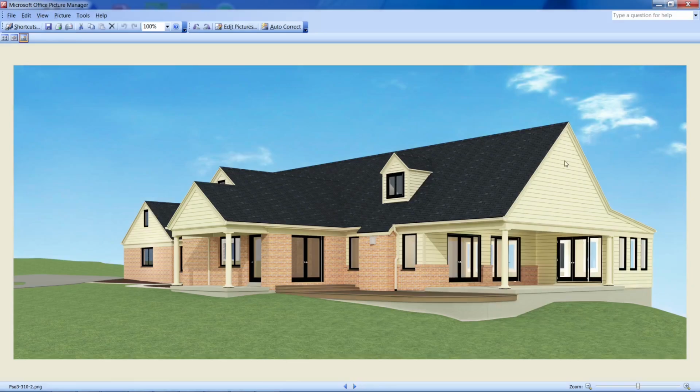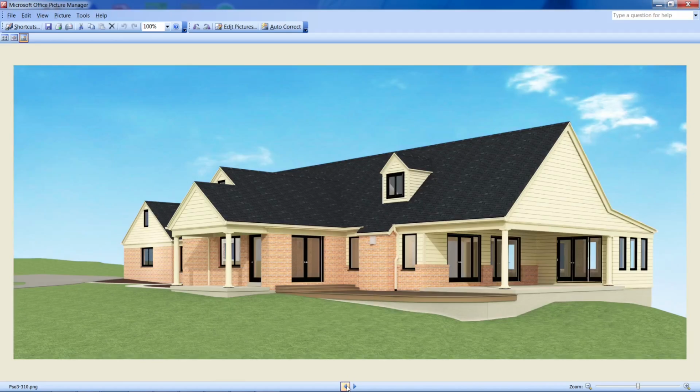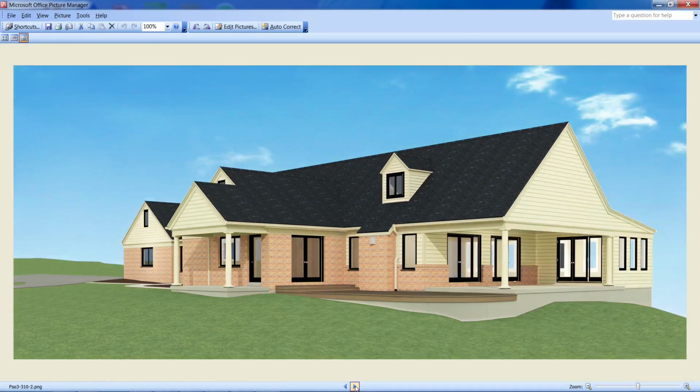And this was just correcting some things up along this roof line. Your current one is built thick like that, where it's a 1.5 inch piece, it looks like, out there. And the new one will be more conventional like that. And remember, this is all still built with traditional materials. All this crown mold is still up here, etc. That would presumably be replaced, as I mentioned in an earlier film. This crown mold would probably be replaced with square stock of some type.